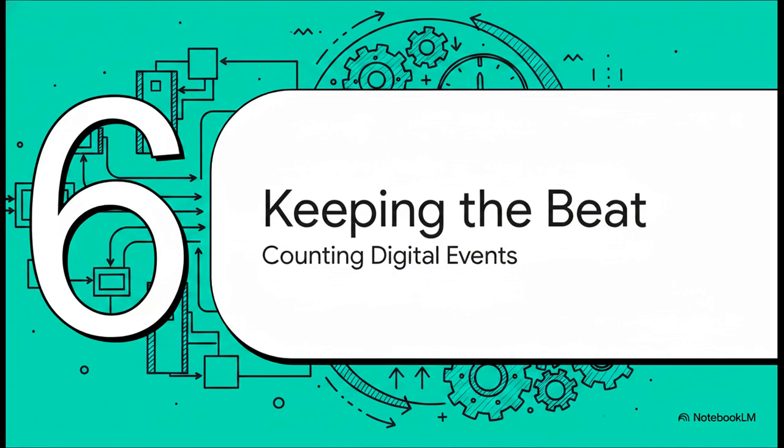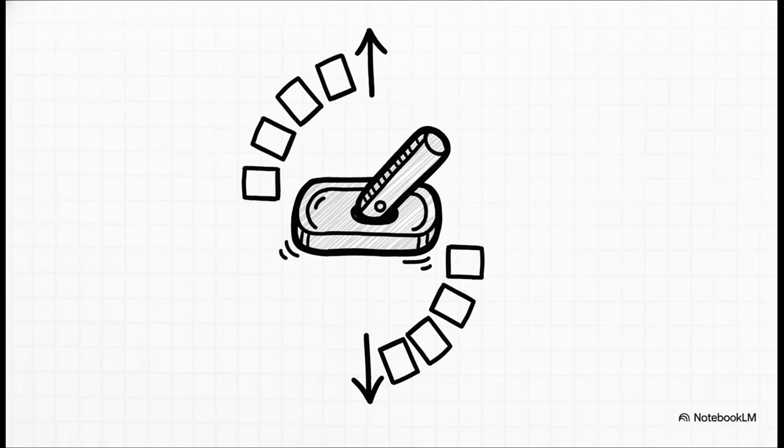We've reached our final high-level assembly today. We've stored data, we've moved it, and now we need to count it. But remember our thematic callback here. Counters are really still just cleverly arranged teams of flip-flops synchronized by a clock. Counters tally up the events or pulses in a digital system. You've got up counters that count progressively forward and down counters that count progressively backward.